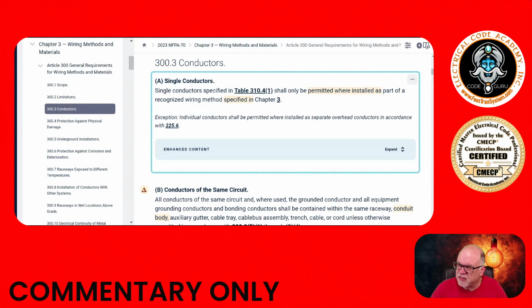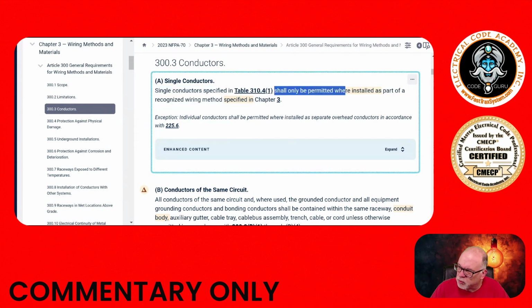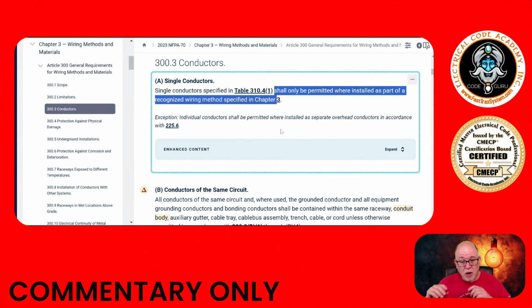It says single conductors, THHN is one, specified in 310.4, which is that list where we saw THHN, shall only be permitted where installed as part of a recognized wiring method as specified in Chapter 3. Well, individual conductors aren't in Chapter 3. That's where MC cable, AC cable, rigid, intermediate, and EMT are. So that's another example that THHN cannot be dumped directly into the earth.